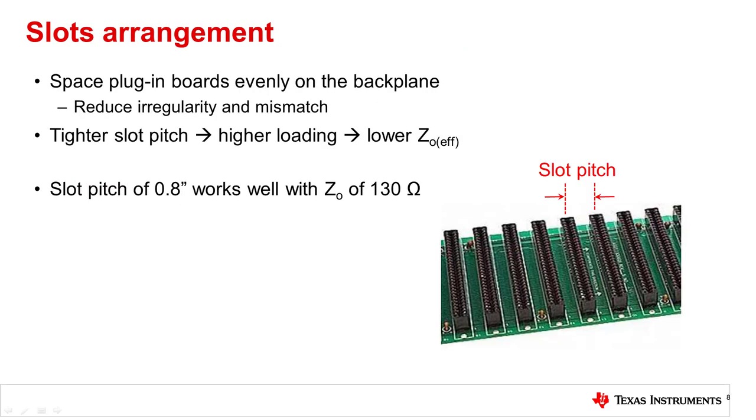The plug-in boards should be spaced evenly on the backplane. This helps reduce any irregularities and mismatch. The slot pitch, which is the slot-to-slot spacing, is normally determined from system considerations such as overall system dimensions and the number of boards supported.